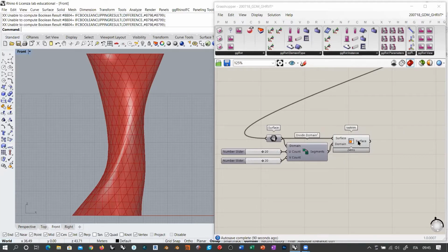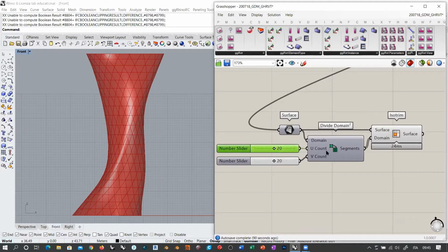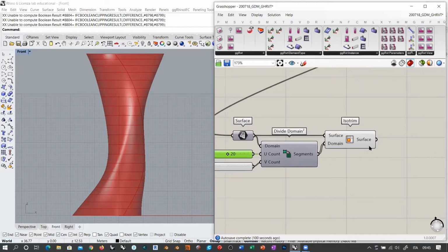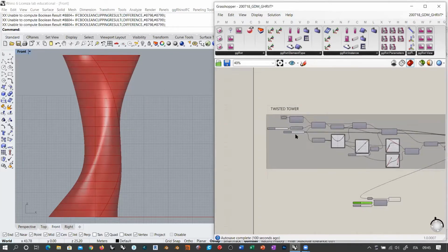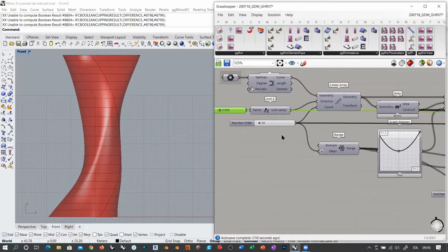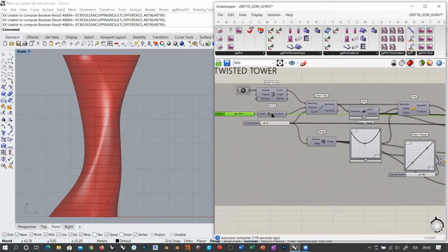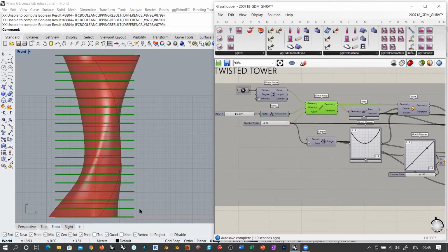So for example, I am dividing this vertically along the vertical axis, like in 20 spans, okay? Which means, by the way, that we will have 20 surfaces, 20 horizontal stripes, okay? 3.5 is actually the separation between the step of this array of columns, okay? And we have 20 count for the linear array.